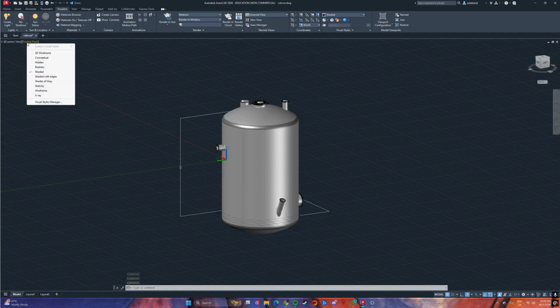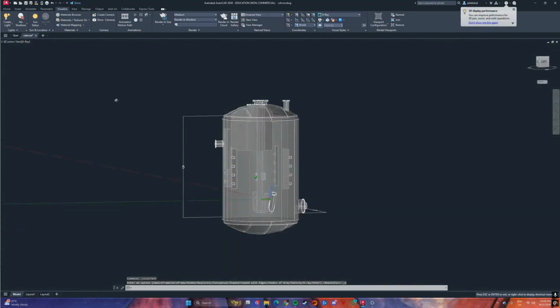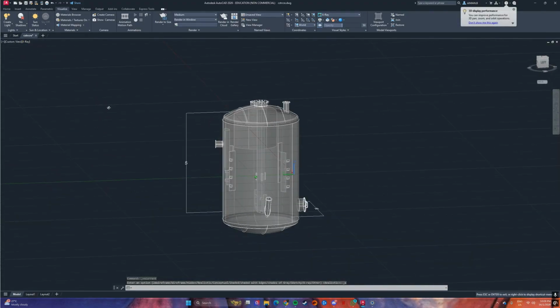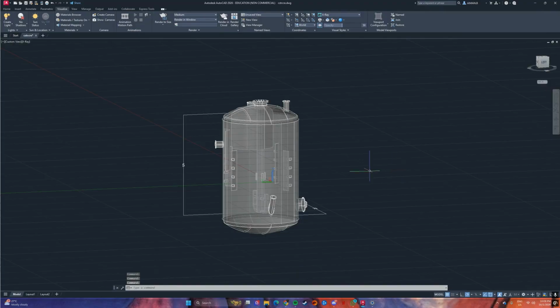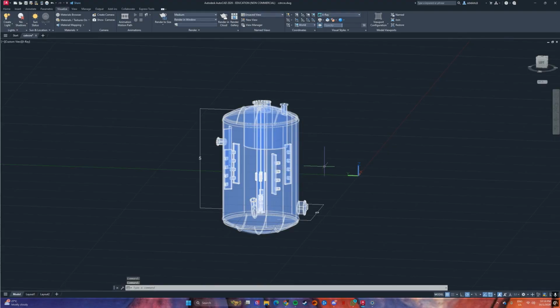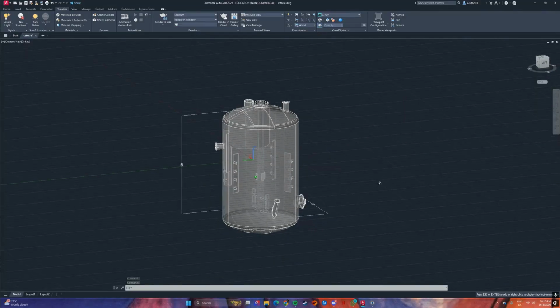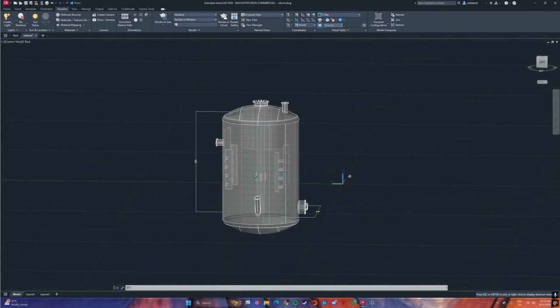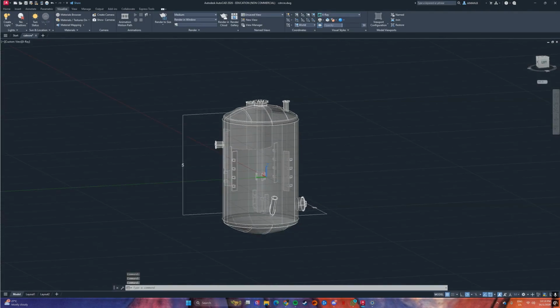And then next is the inside of the tank, where we can see we will have the stirrer, which is able to ensure that everything inside the tank is mixed well. And also we have the plates or baffles inside the inner wall to ensure that the mixing efficiency increases and also the heat transfer. So this is basically the design of our CSTR.